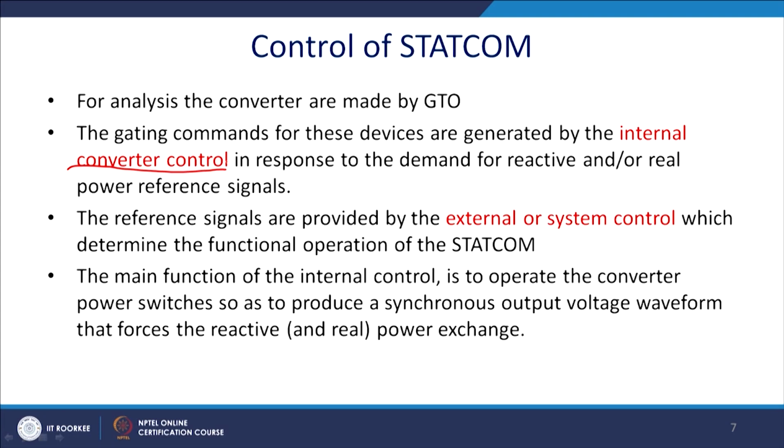The reference signals are provided by the external or the system control, which is determined by the functional operation of the Statcom. The main function of the internal control is to operate the converter power switches so as to produce the synchronous output voltage waveform that forces the reactive and the real power exchange. So, this is the way of controlling the Statcom.